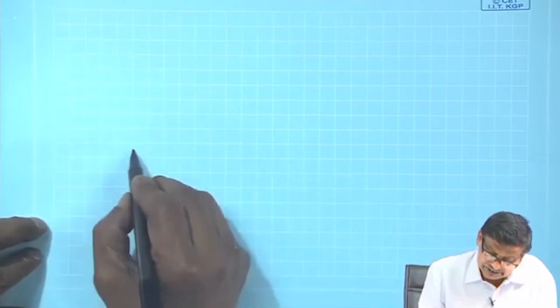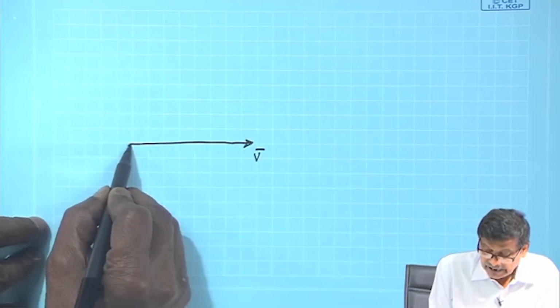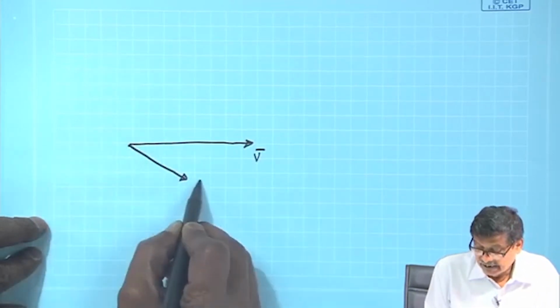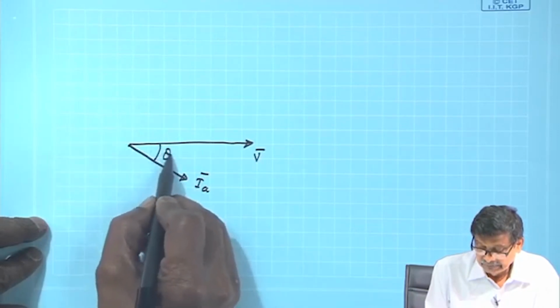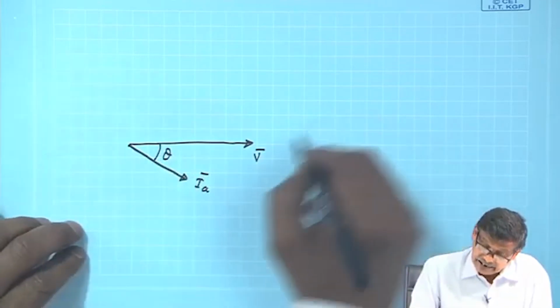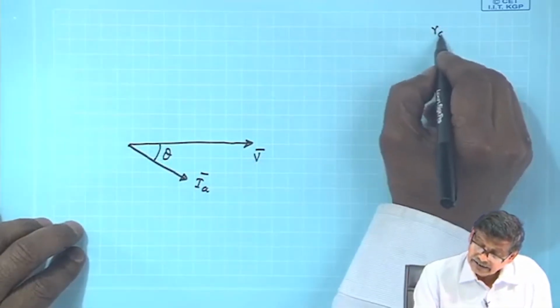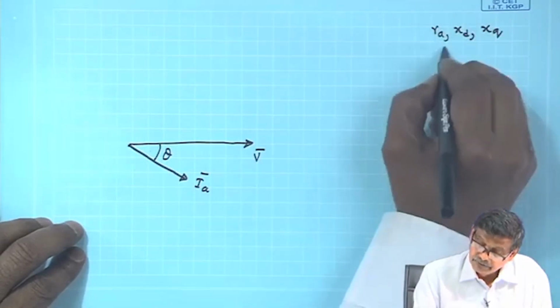So, from the operating point I calculate delta, then I will do the phasor diagram much more confidently now. It is like this. I will sketch V, I can also sketch Ia and theta; these are the known things, and then Ra, xd, xq are known.